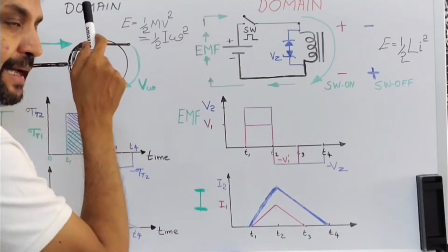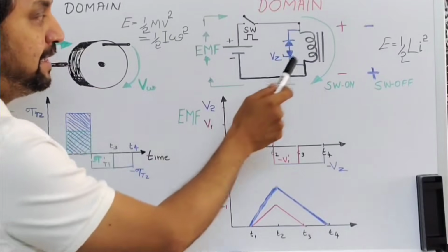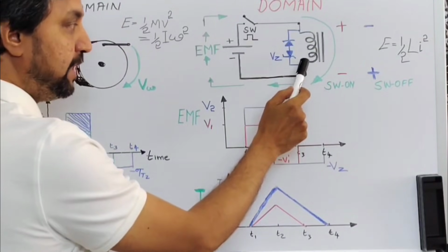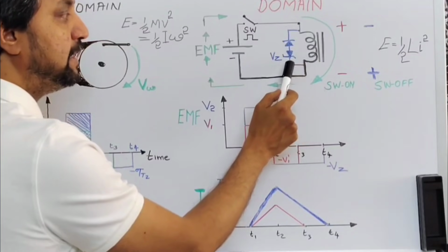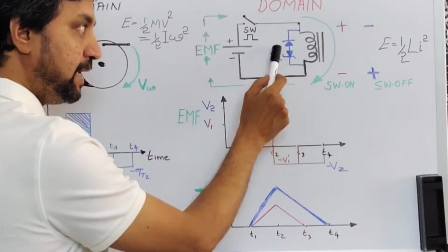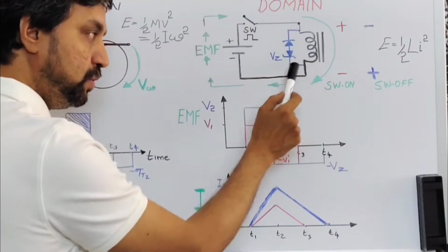Like the way this inertia wheel created a force, the inductor will create an electromotive force. It generates a voltage equivalent to this Zener voltage and the drop of the diode, and tries to discharge the inductor through this channel.